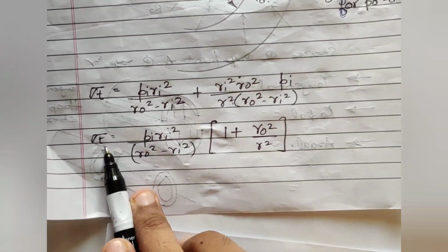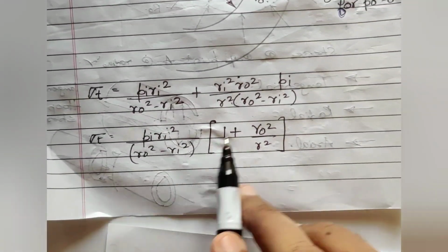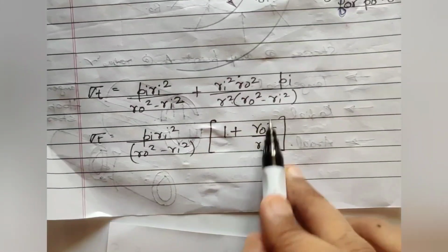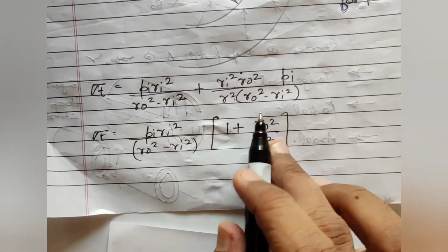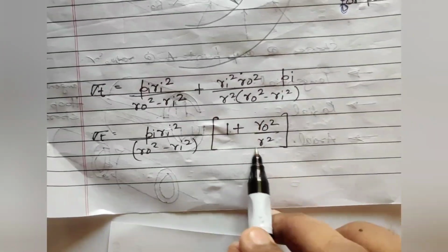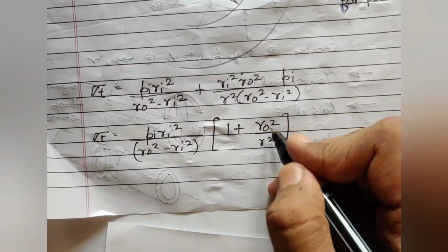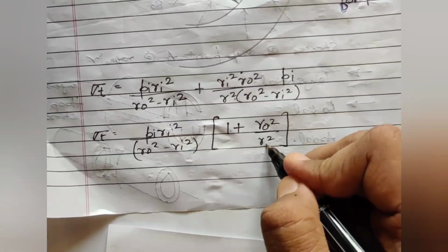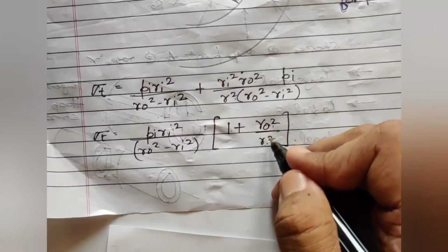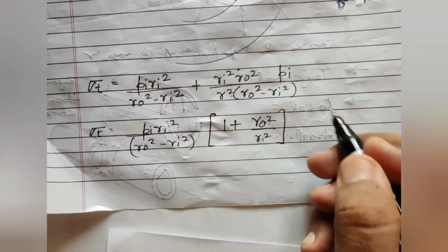So you get the tangential stress or hoop stress as Pi Ri square over Ro square minus Ri square, into 1 plus Ro square over r square. As r increases, this value will decrease, and as r is reduced, this value will increase. So on the inner periphery r will be Ri, and this value will be maximum. Say Ro is 50 and Ri is say 25. In that case this will be 2, and as you move towards Ro, r will become Ro, so 50 by 50 will become 1. So on the inner periphery it will be maximum, and on the outer periphery it will be minimum.